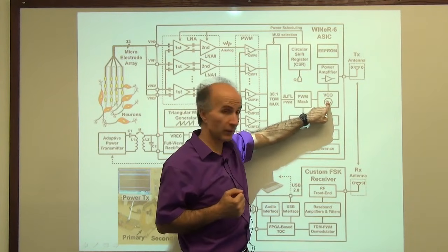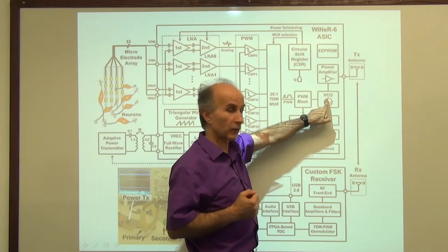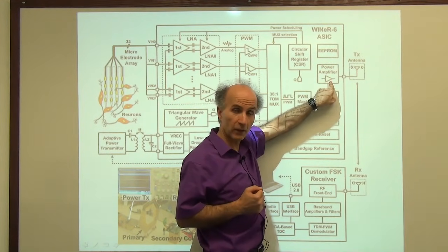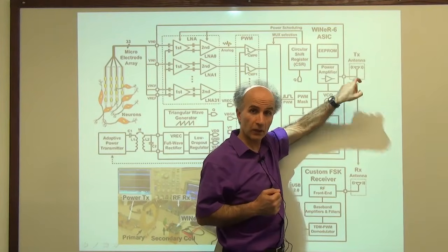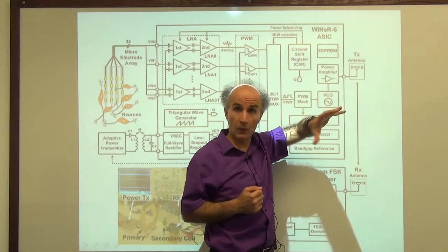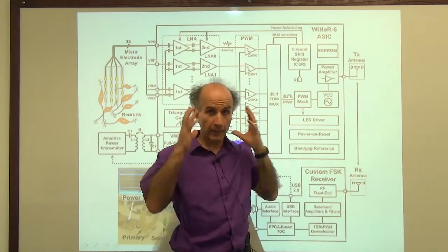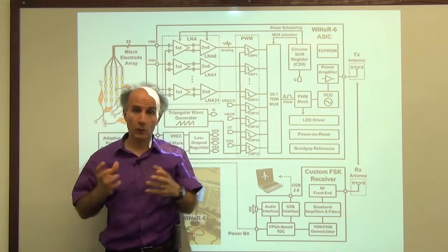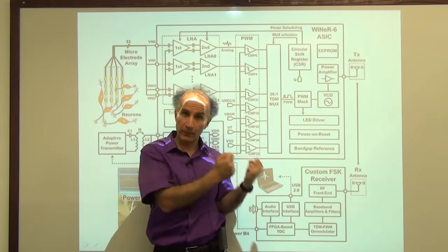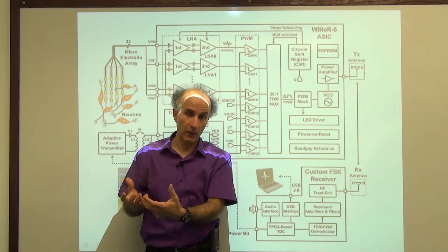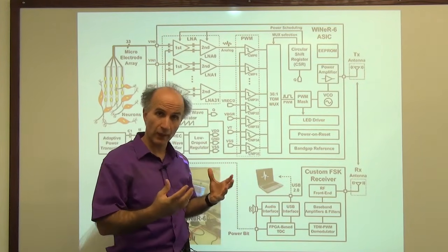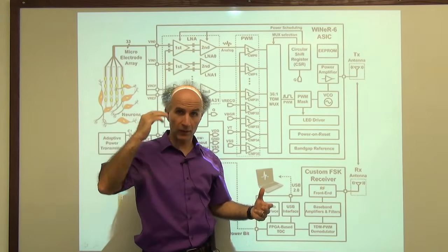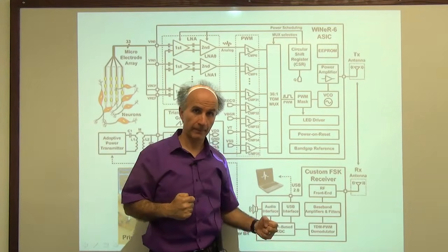We modulate the frequency of this oscillator. The oscillator drives a power amplifier to deliver more power to the antenna. And this information is transmitted wirelessly. Why wirelessly? Well, because the patient wants to move around. You don't want to have so many wires hanging from the patient while the patient is moving around. So for that tetherless application, it's very nice to have a wireless connection between the patient and the monitoring system.